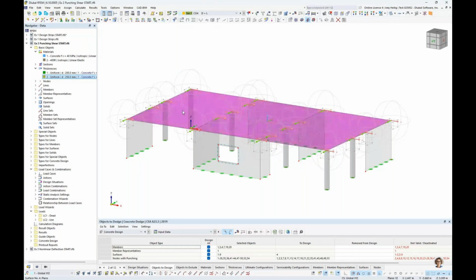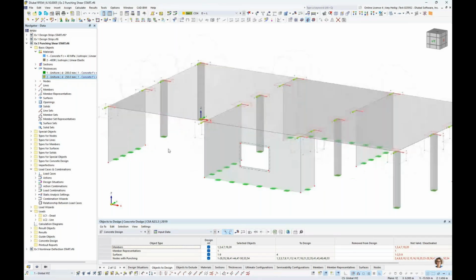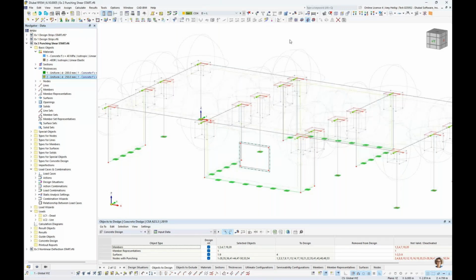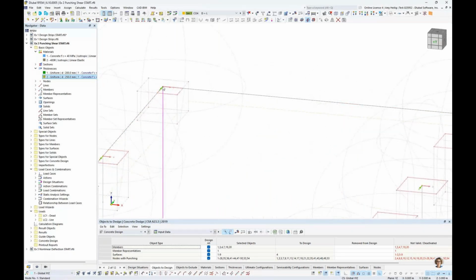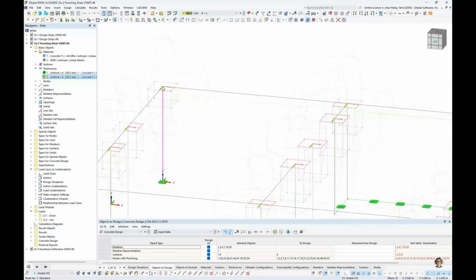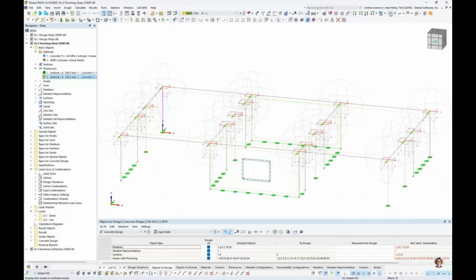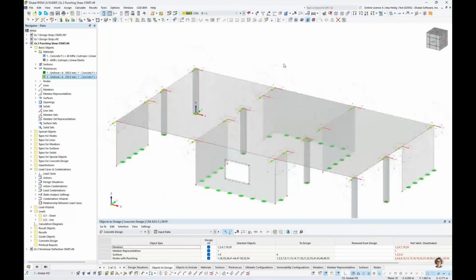But because I'm going to carry out the design according to the FEA method of this elevated slab, inevitably we're going to have what we call singularities. And singularities are not unique to RFEM. They happen in all FEA programs. The reason why is because we have these column elements, for example, that are framing up into the 2D surface, and all forces are being transferred at this single FE mesh node. But we know in reality, we're certainly getting better load distribution than just that single mesh point, because our column is certainly going to have dimensions here.